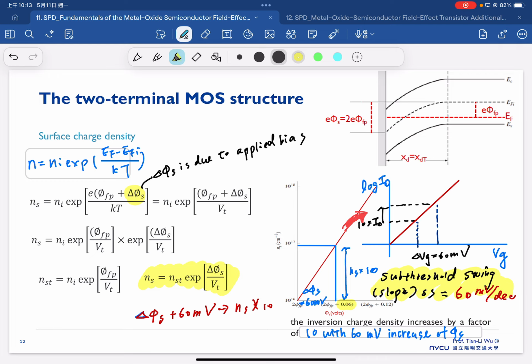But indeed, in the semiconductor community, we have some very interesting technology that can possibly break this fundamental rule by taking into account additional physics, additional understanding, and by using novel materials that create novel physics, and in the end we can break this rule. But still, 60 millivolt per decade is a general target, but also a limit for most of the CMOS transistors.